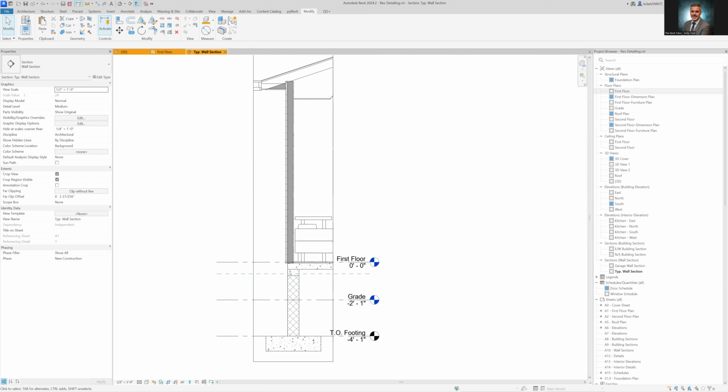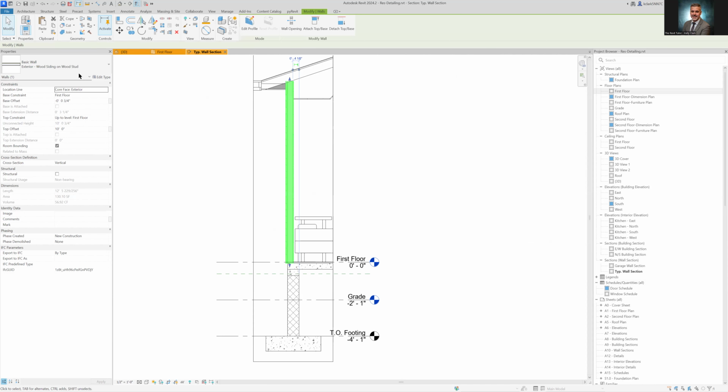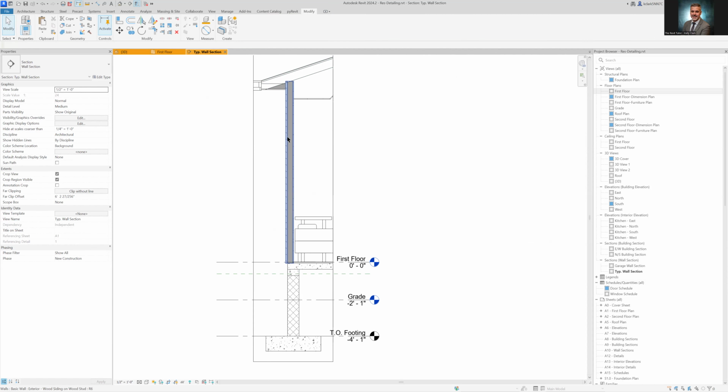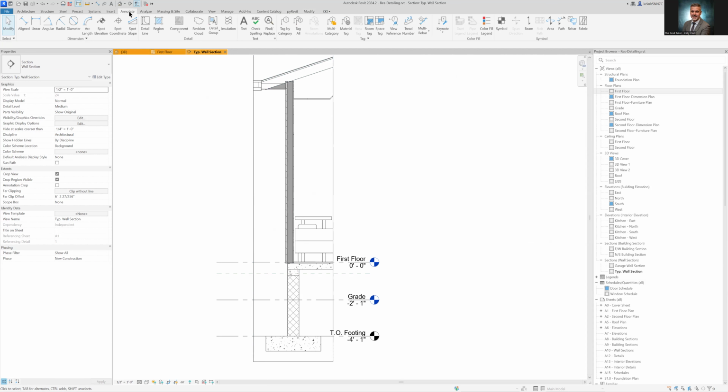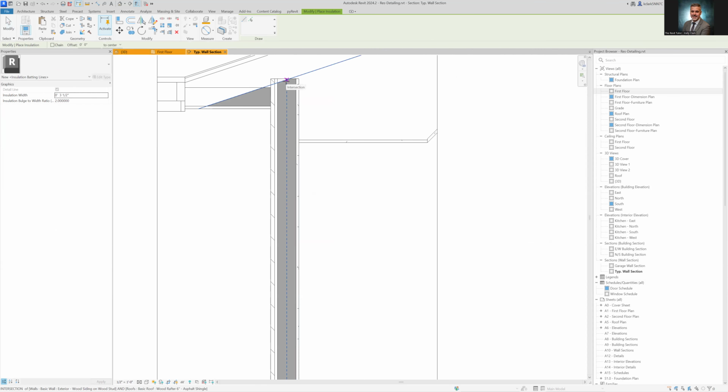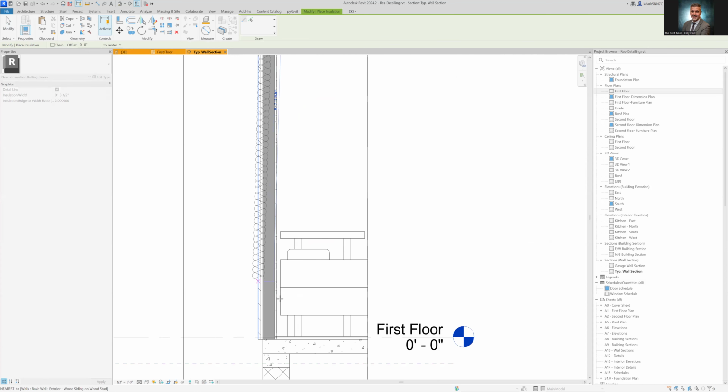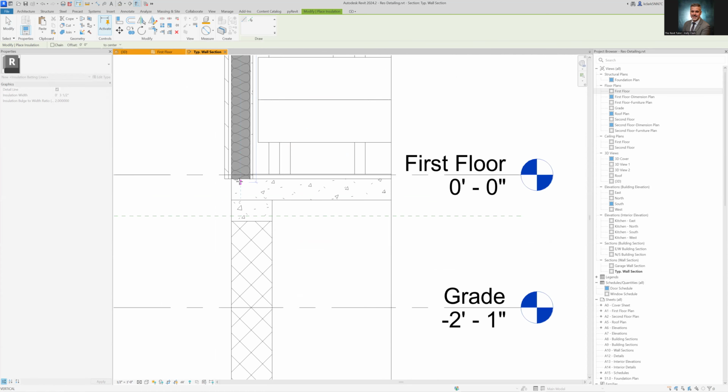So to do that, I'm going to put in the insulation that goes right here in the stud of the wall. For this particular wall, this one is a wood stud, so we would insulate it. It's on the outside of the building. So go to the Architecture tab, and actually, my apologies, it is an annotation. Get in the insulation, and it snaps to the centers. So you can see that dash blue line is making that up for me, so I can click, and I can drag it along all the way till I get to the bottom.